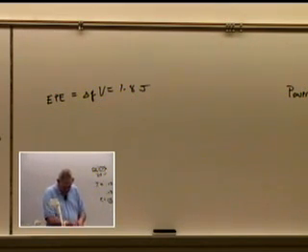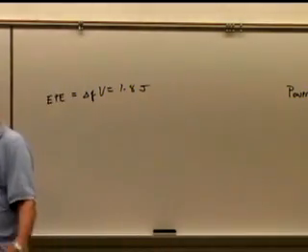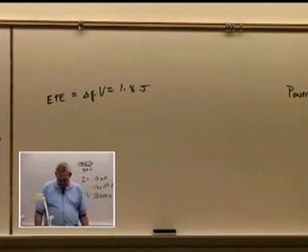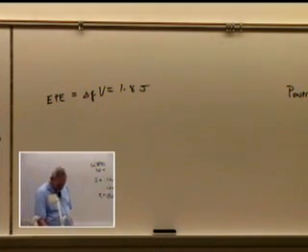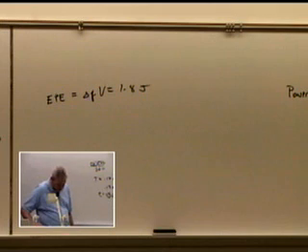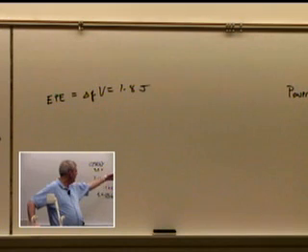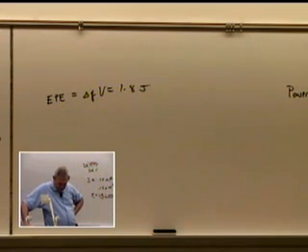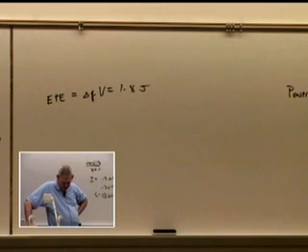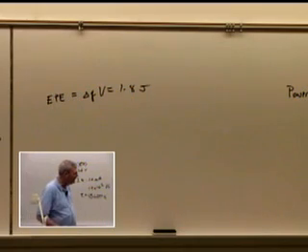The filament in a light bulb is a resistor. It gets very, very hot, and so it burns red hot and gives off light. It's a thin piece of wire, tungsten, actually. The wire becomes hot enough to emit light because of the current in it. Okay, all right, and so that one little circuit that I drew up here was an example of a flashlight battery. A flashlight that uses 3 volts provides a current of 0.4 amps in the filament. Determine the resistance of the glowing filament.